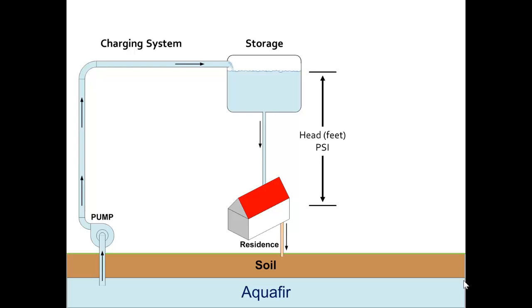Now, if this tank were twice as large in diameter, but the water level still was no higher than what you see here, the head pressure would remain the same. Even though you're thinking, well, there's more water up there, this is done with a vertical column. So if you travel straight up the pipe, and when you get to the bottom of the tank, you keep going straight up to the water level, that's what you're measuring.